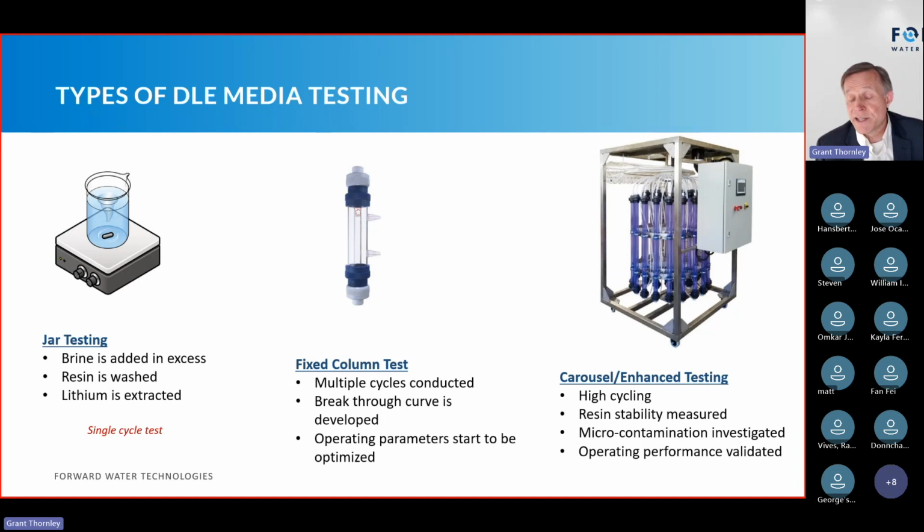Now, that being said, if you're increasing the temperature, then you're adding energy into your process, which means you're increasing your costs. So again, the economic viability, you need to model that out. But if you're seeing that your absorption is low, the first thing I'd say is, look, increase the temperature and see how that improves.